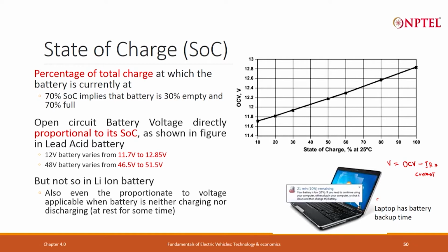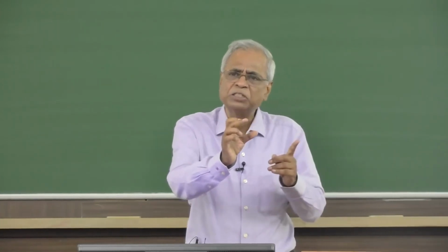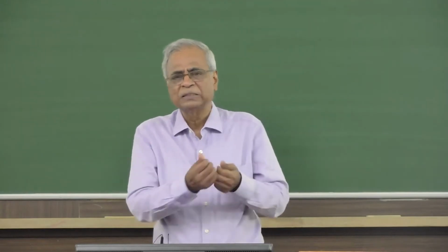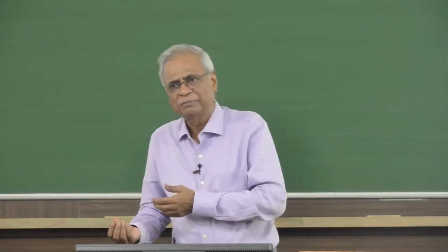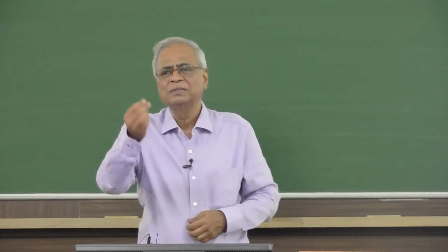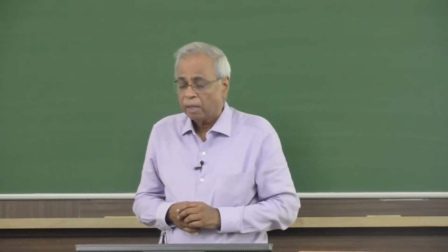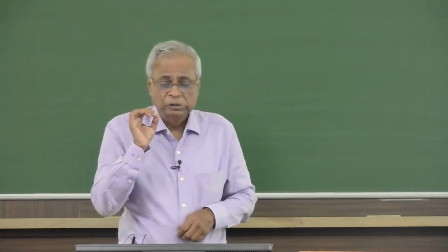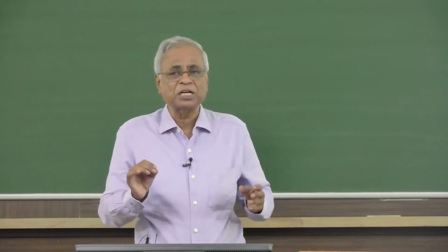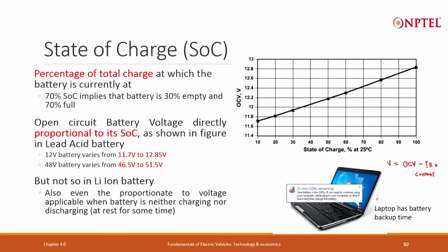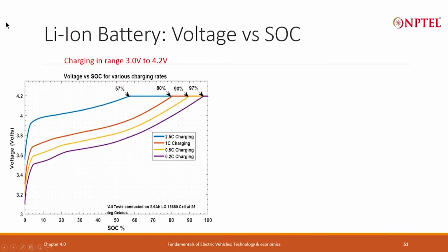If it is part of the battery, there will be a BMS which will measure the voltage, convert it into numbers and store it, or even transmit it through a CAN interface that a battery may have. That will give you the voltage, but what will be the state of charge? For a lithium ion battery, it is not linearly proportional. So, what is there for a lithium ion battery? And this is a very important learning.